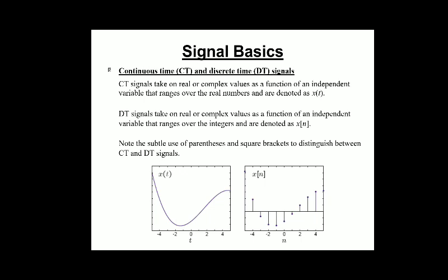Now suppose instead of sharing your location continuously with me, you are calling me after every 15 minutes and telling me your location. And on the map of West Bengal, I am putting a dot on the location every time you are telling me your location. When you reach Darjeeling from Kolkata, I connect those dots by straight line, and now I have approximate path of your journey, which may not be exact because in between those 15 minutes, you could have taken a circular path, and I would not have known it because I have connected the dots with straight line. So now this is what we call discrete time signal. Note the use of parentheses for continuous time signals and square brackets for discrete time signals.